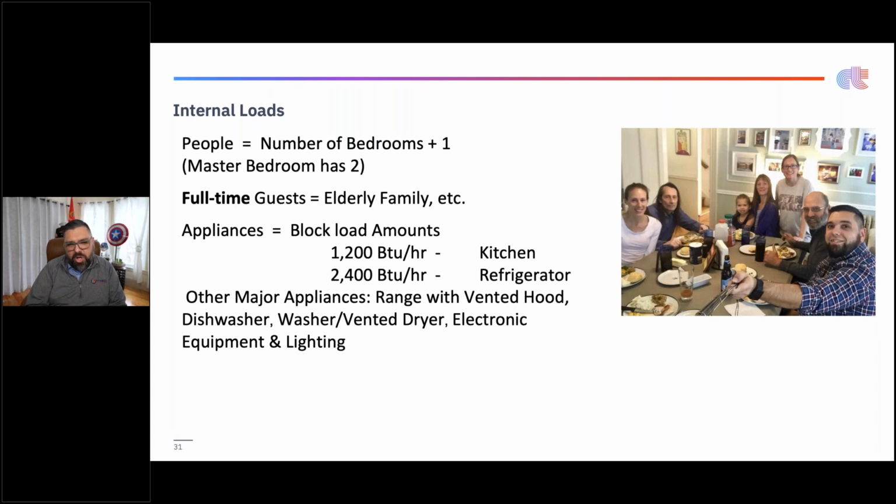There is a third option, scenario number 3. I apologize, it's not on your slide here. Scenario number 3 is 3,400 BTUs, and it actually accounts for multiple refrigerators. We see this a lot because people might have a freezer or a second refrigerator in the conditioned space that puts off more heat, and we have to account for it. But it's not just that.